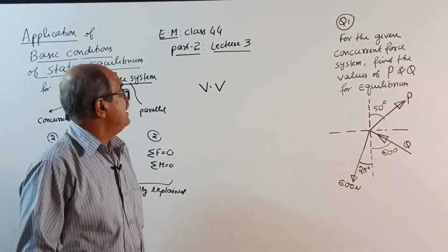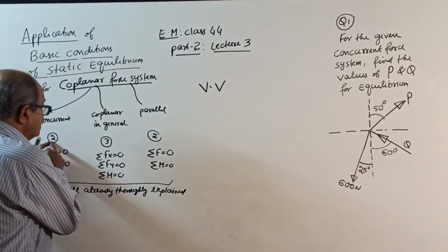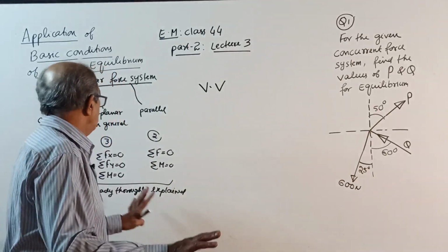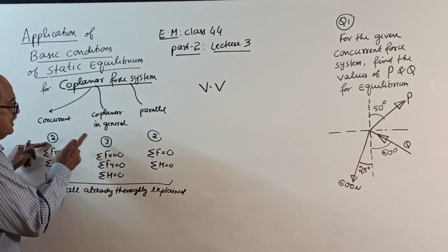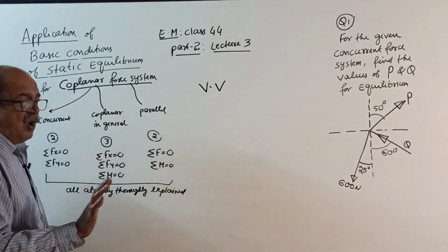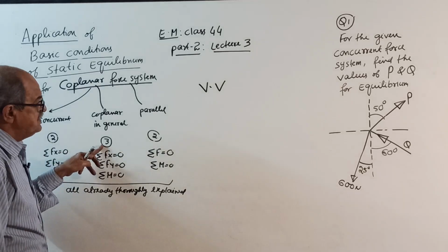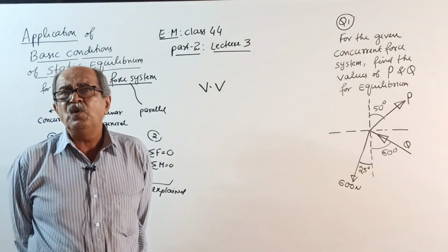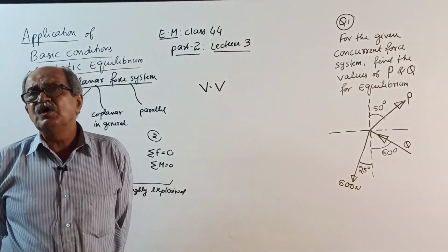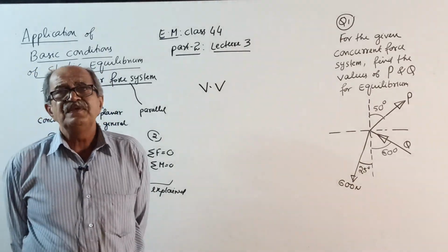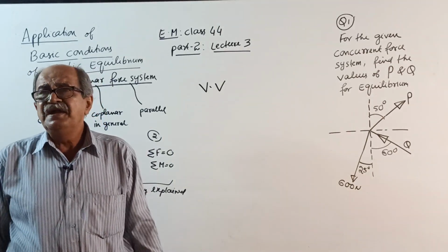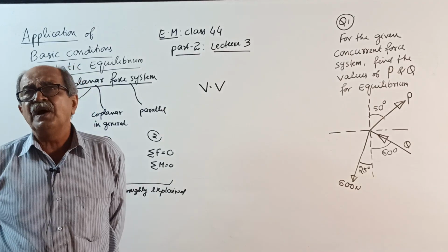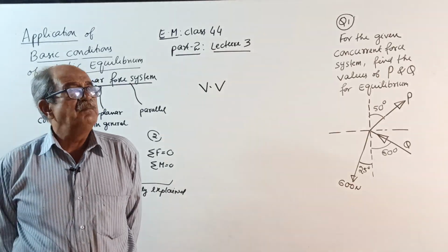Consider a case when there are 2 unknowns, 3 unknowns, 2 unknowns, against 2 conditions, 3 conditions, 2 conditions. I told you unknowns can be either equal to conditions or more. Equal means determinate. More means what? Indeterminate, excess unknowns. Okay. But suppose the number of unknowns is less than the number of conditions.